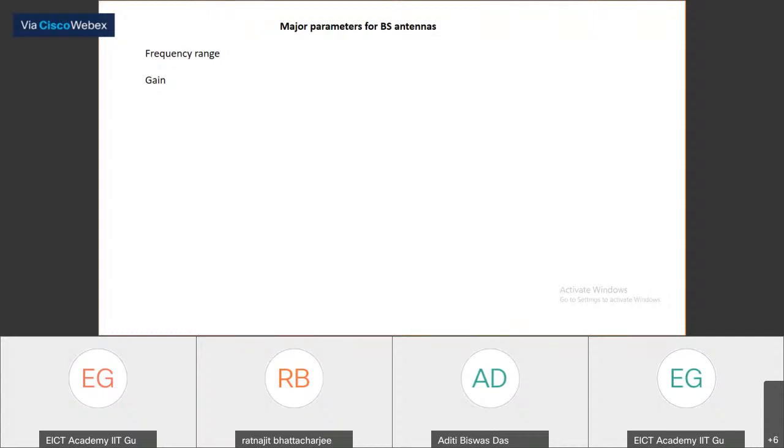So if you multiply the directivity function by that efficiency of the antenna, that will give you the gain function. And gain function is again a function of theta and phi, and the maximum of that we call the gain. If you have a directive antenna, the direction in which the maximum radiation takes place, and if you measure the directivity function and multiply it with the efficiency of the antenna, you will get the gain in that direction. So gain of the antenna is usually specified.